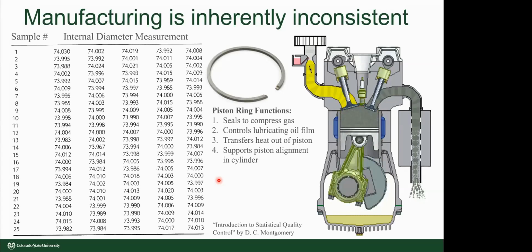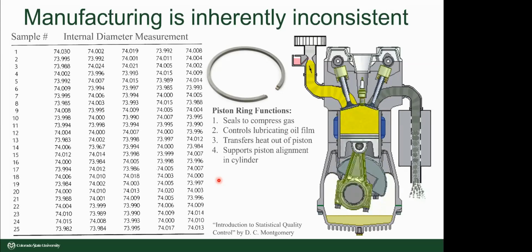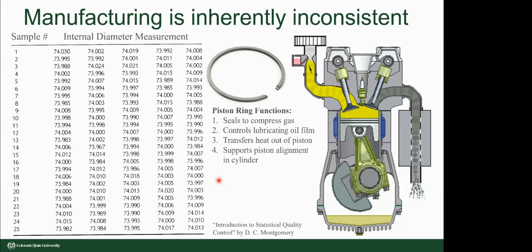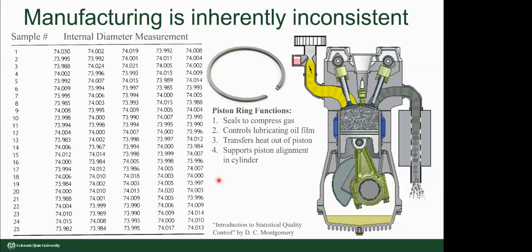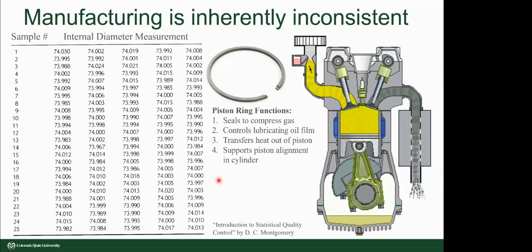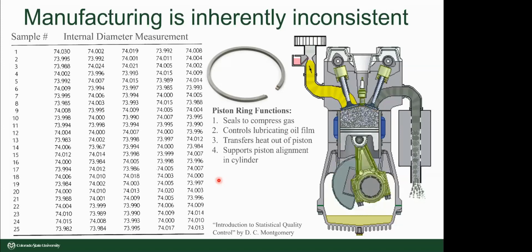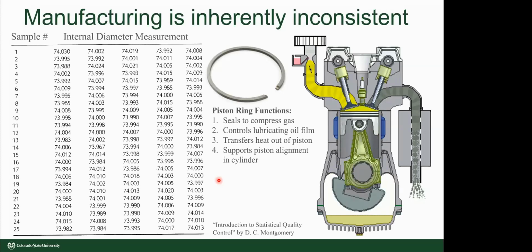Tolerances are used to control the manufacturing variability to a level that is still cost-effective, yet produces an acceptable level of reliability for the assembly and the functionality of the product. So the term tolerance is the total amount a dimension may vary from the ideal value for that dimension. In other words, tolerance is the difference between the maximum and minimum acceptable limits of a dimension.